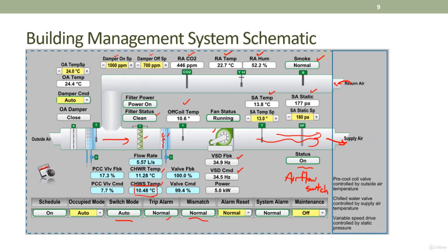The good thing about BMS is that all this data is also trended, which means it is being logged. So all these data are saved. Let's say I want to find out what was wrong with the temperature last week Tuesday. I want to take a look. You will be able to do so via the BMS, because the server will save all this data. So I hope you have a better idea on how to interpret either a mechanical drawing, a CAD drawing, or a BMS schematic.